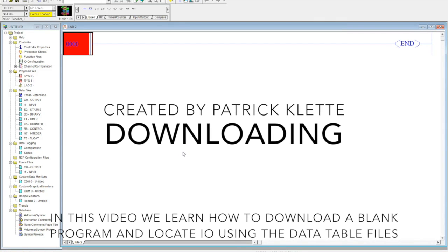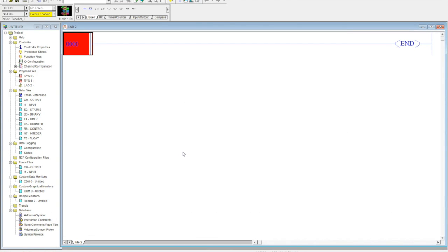Okay, in this video, I'm going to show you how to download an empty program to your PLC so you can attempt to figure out which inputs have what field devices wired to them. Here I have a blank program set up. We've already done our RSLinx, set that up. We've already done our controller properties. We have that set up. We've configured our I/O. And so now we're ready to download a blank program.